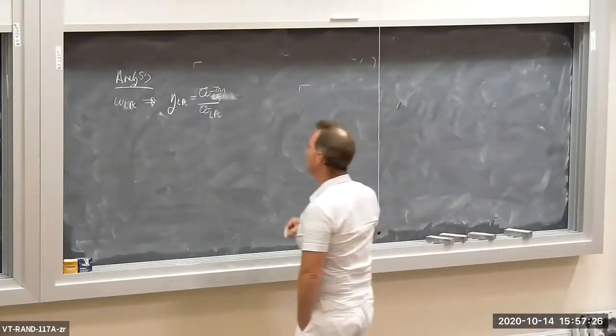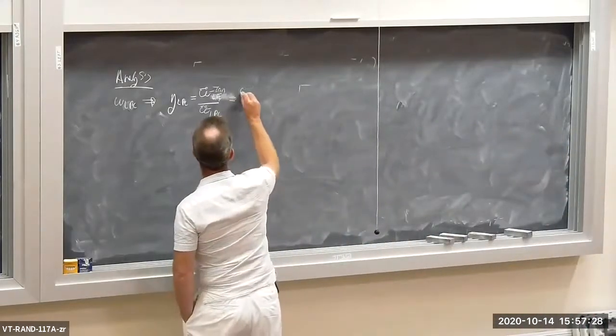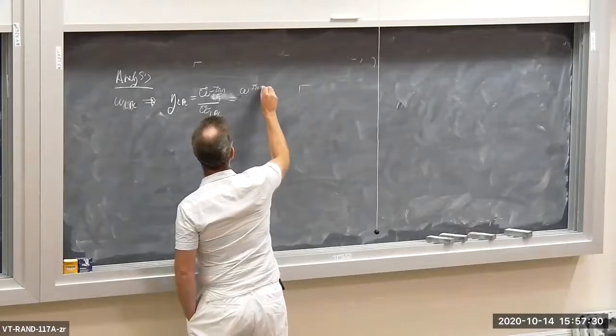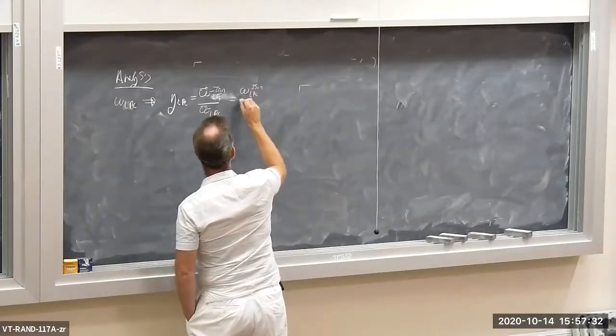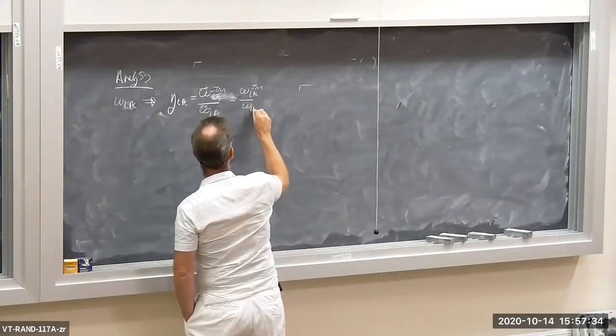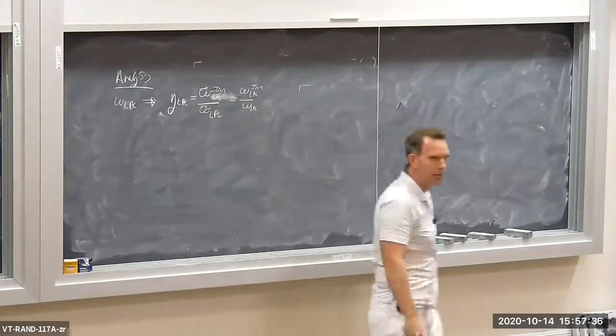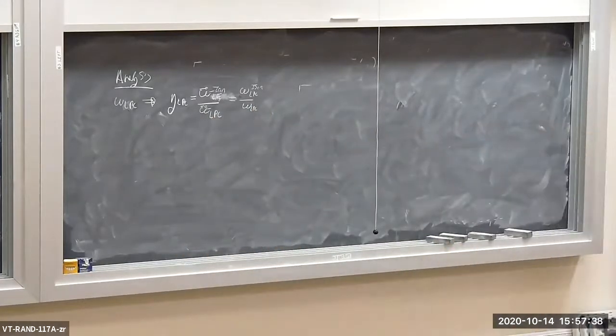Of course, I can write this in terms of specific work, W_isen,LPC over W_LPC, because the mass flow rates are the same in the isentropic and the irreversible non-isentropic LPC.